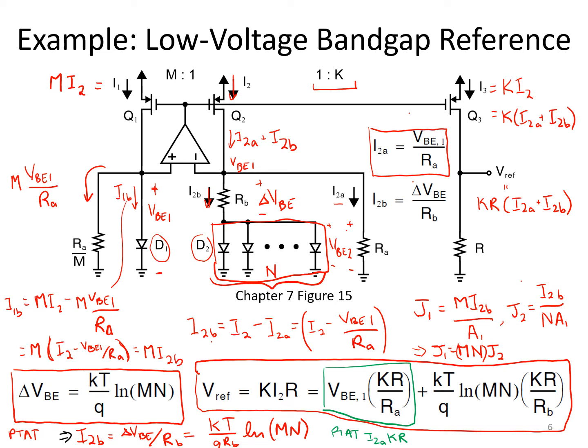And you'll notice the temperature coefficient of the resistor RA should be perfectly canceled by the temperature coefficient of the other resistor R. So the intention here is that both R and RA, and in fact the other resistors in the circuit as well, RB, RA over M, should all be realized in the same way, using the same style of resistor, for example, polyresistor, and should be matched with ratiometric techniques so that all resistors are either parallel or series combinations of the same elementary unit polysilicon resistor.